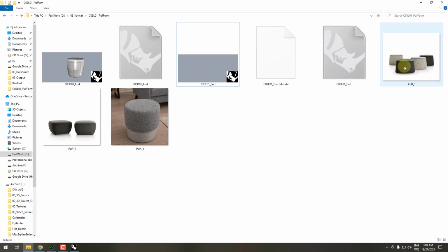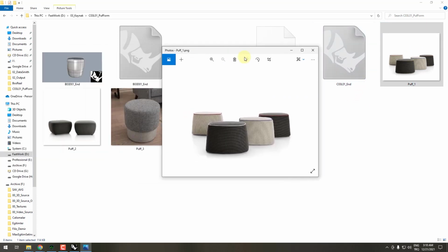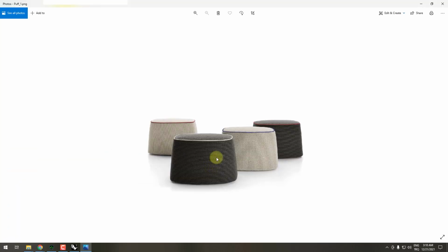So if we were modeling this path with standard Rhino processes, we would possibly start drawing curves for this geometry. But in SubD modeling, we usually don't start with curves. We start with basic shapes. So the first thing we must consider is what's the simplest, most basic geometry for this model. As you can see, this model can be achieved by starting from a box geometry.